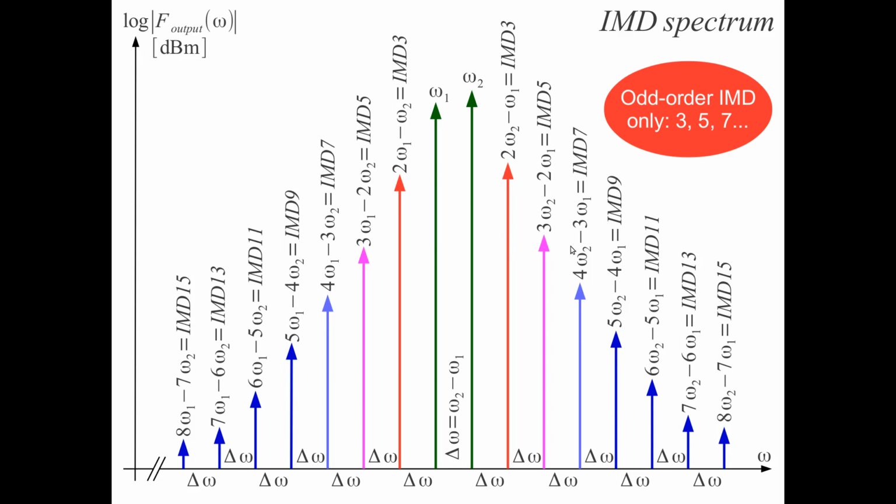And in fact, next hour we are going to see in detail how to calculate this spectrum, the magnitudes of these spectral lines exactly. We know the positions, given by delta omega. The actual frequencies are very easy to calculate, but for the magnitudes, we have to find methods to calculate the magnitudes of this distortion happening in our amplifier, and also how to specify the amplifier in terms of distortion, to keep the distortion low enough for our intended purpose. So next hour we are going to calculate the magnitudes of the various spectral components we have here.